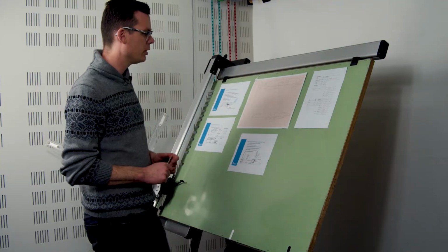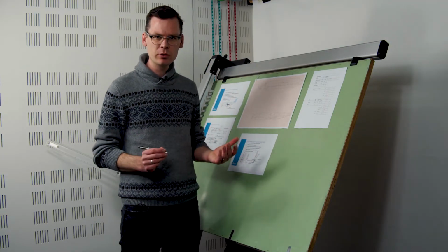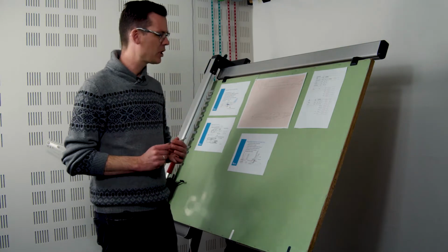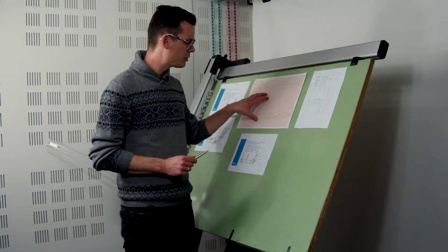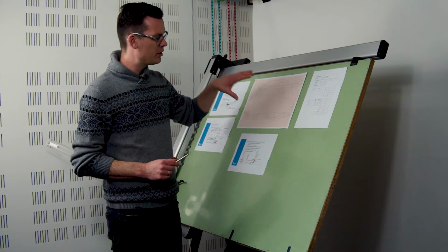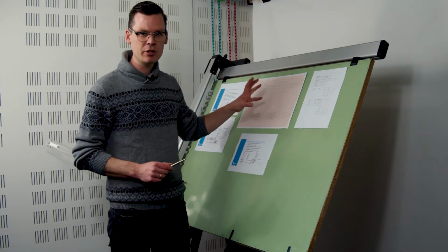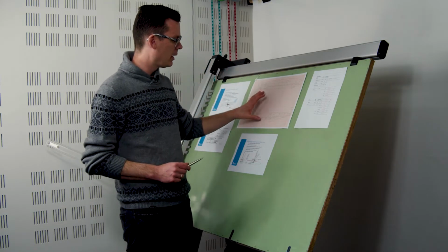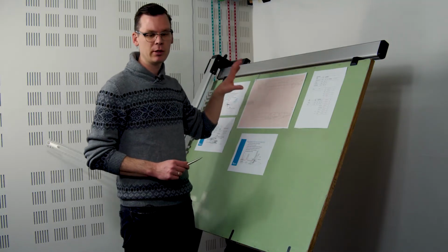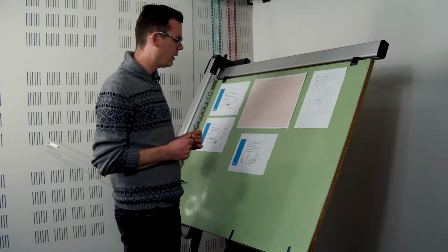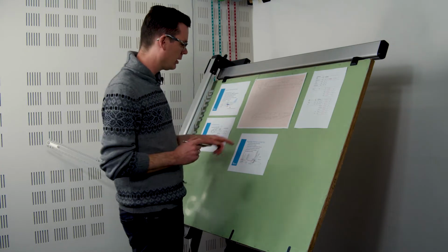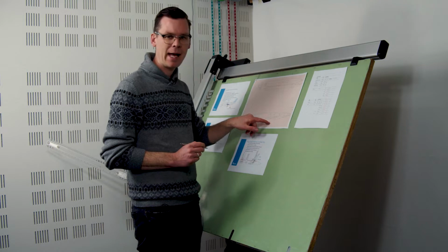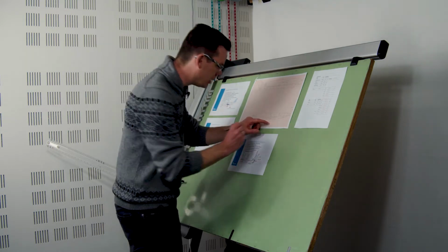Right. Now, prior to this exercise, I'd already determined what the size of the wheels was going to be based on the maximum takeoff weight of this airplane, which is 570 kilonewtons. Based on that, the load classification number of the runway, we estimated the tire pressure, and from that estimated the main wheel diameter. That turned out to be 1 meter, which means I can now draw in the wheel here about that axle point of about 1 meter.